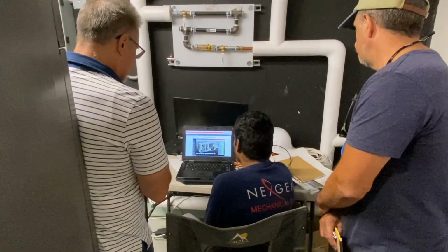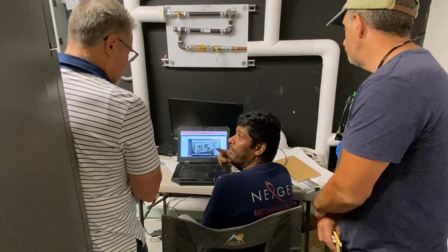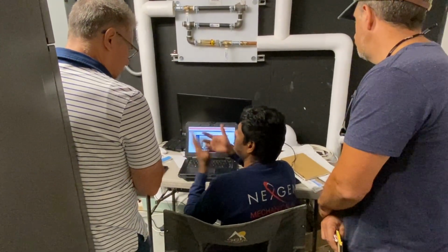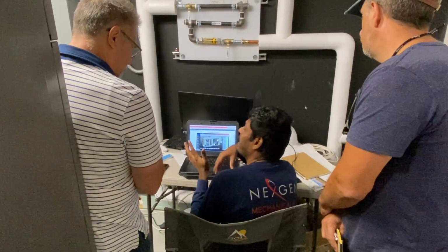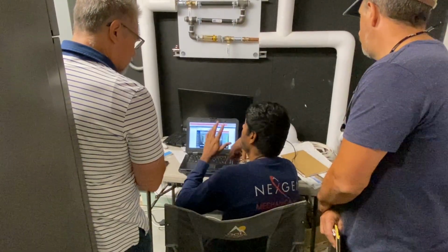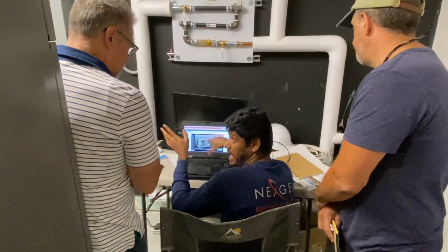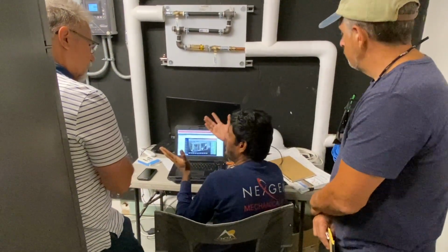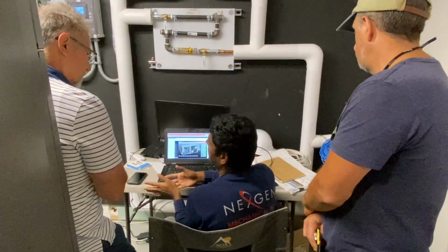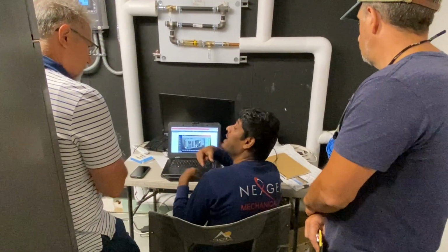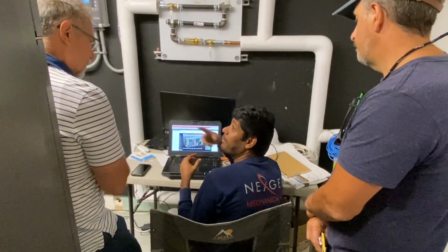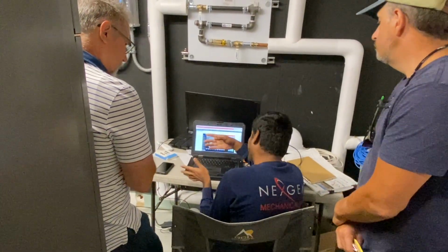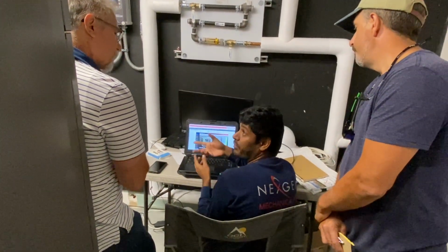And what else? Again we have the energy wheel operation. The energy wheel operation is based on the enthalpy; it's going to decide when I have to run. If the exhaust fan is on, I'm going to run it because I'm going to pull air through the wheel. There are some conditions: if my exhaust fan is on, if my economizer is on, or if my enthalpy is satisfied, then I'm going to run the energy wheel. It can be used for cool recovery, or it can also be used for heat recovery.